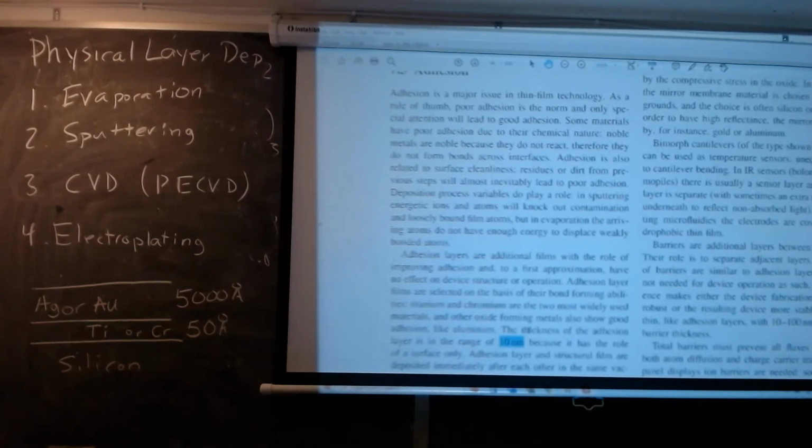So now the thing is that, okay, silver's not as nice. There's a lot of applications, particularly for solar cells, where people just use silver straight. And they don't worry about this next issue, which is that silver doesn't form an oxide in air because it's a noble metal, but it will do what's called tarnishing, which is where it reacts with sulfur in the atmosphere to produce a tarnish.